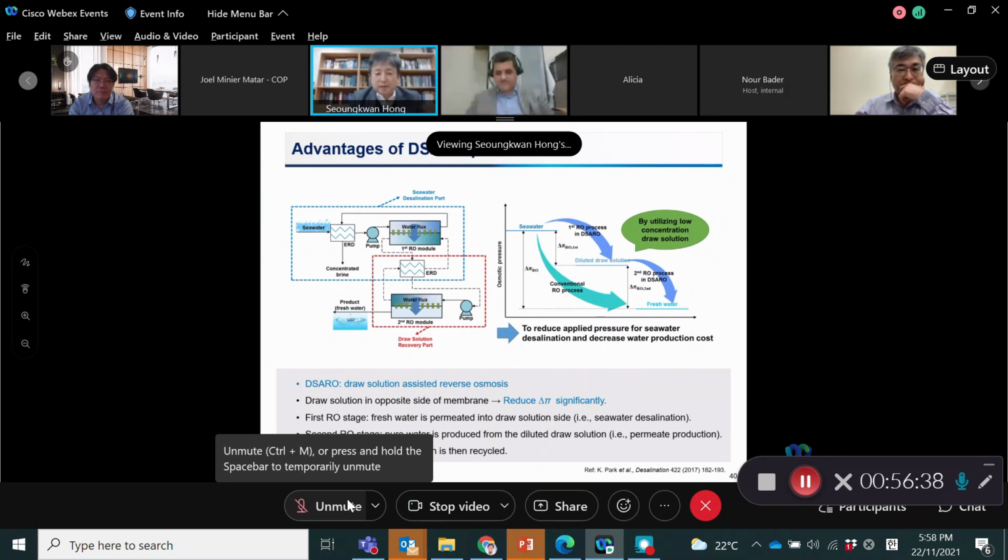So yes, solution composition also affects SEC. From a practical standpoint, if you have a large amount of divalent cations or anions, it is going to affect operation of the RO process due to scaling potential.